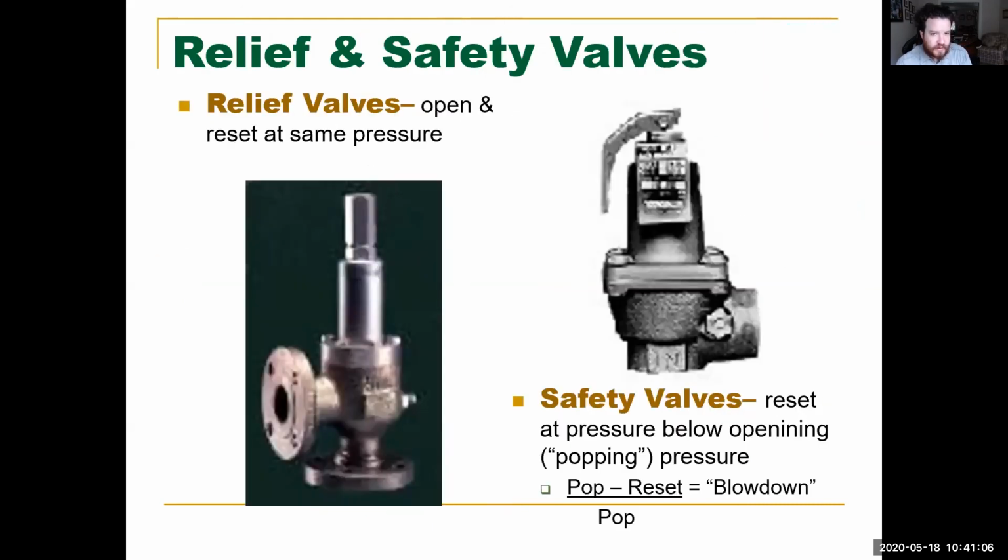So again, like we talked about earlier, the relief valves open and reset at the same pressure, whereas a safety valve opens at a certain pressure, it goes down to another pressure, and then it will only open at that certain pressure. So it gives you a little bit more room instead of just hearing chattering.